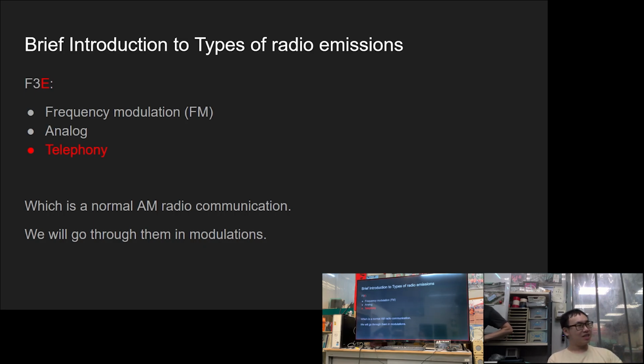Yes. So the F stands for FM. Okay. 3 stands for analog. So we have digital and analog. 3 stands for analog. And the last letter E is the emission class that we have just mentioned. E means voice, telephone. Yeah.